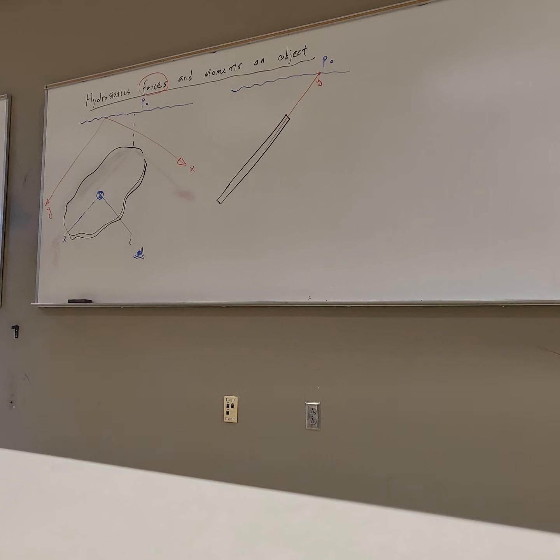So what should I do? Well, if I go back to my basic definition of the two-dimensional element, you remember that we did in mechanics of materials. We had sigma x, sigma y, and then there was a tau xy, just like that. This element is in equilibrium, it's not accelerating, so all these forces from the stress distribution should be in balance.